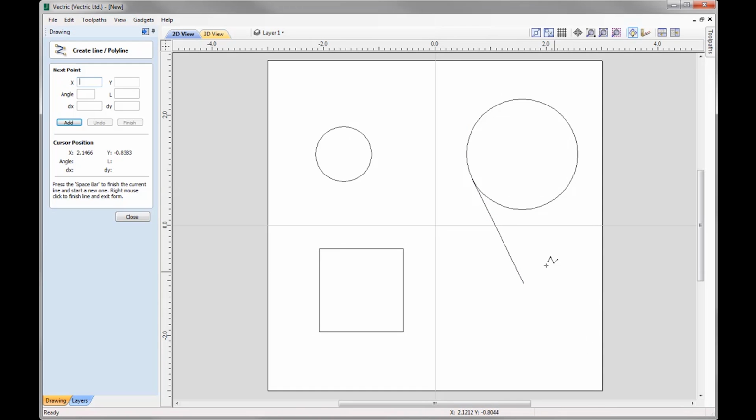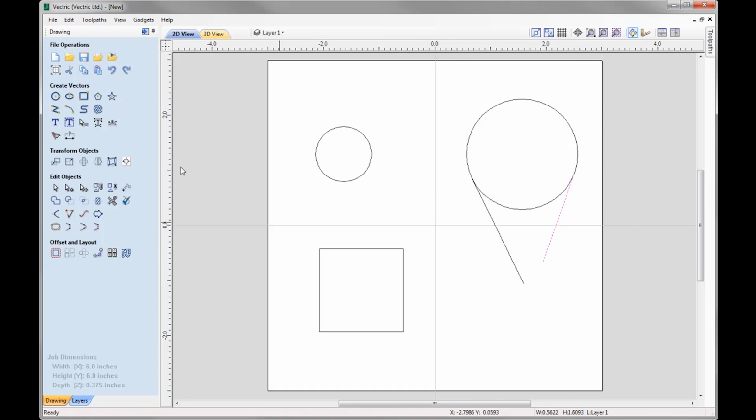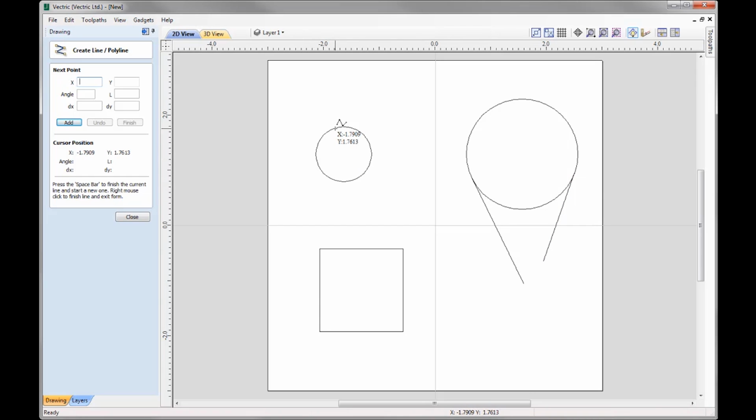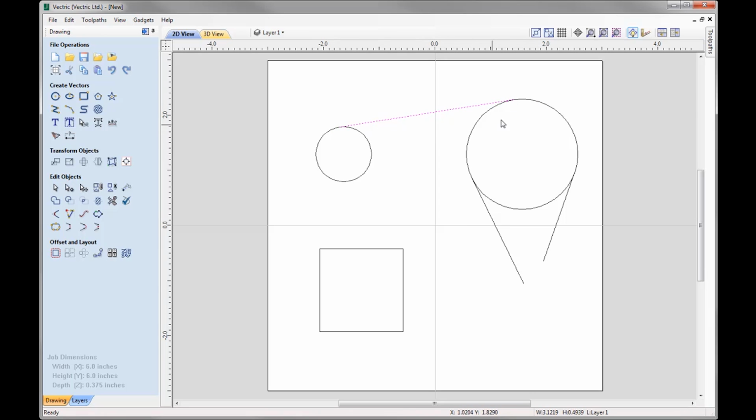So you see that again, so let's just go over, hover over the circle, press T, and then that will create that for me. Okay, going between 2 circles, simply click on the one circle, click to another circle, then press T, and then it will create the tangent line between the 2 circles there. So very handy tool for us to be able to accurately create these lines.